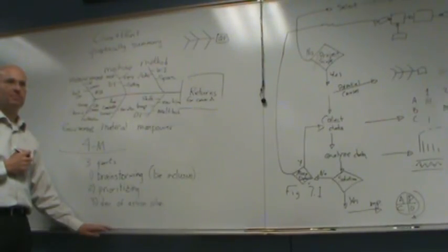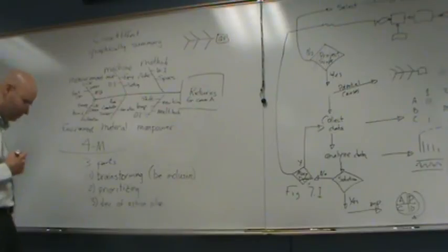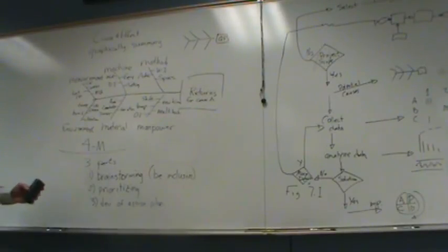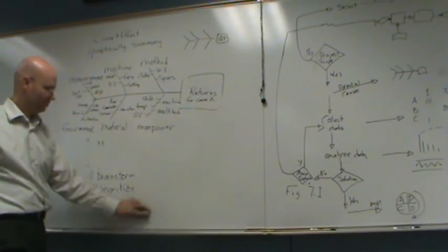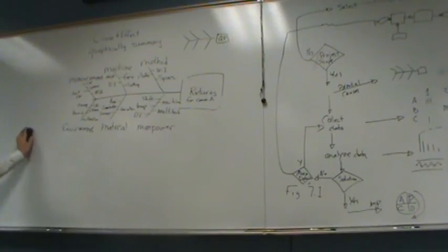And in a lot of cases, you change the ones that were wrong, you do work instructions. We got returns because we got a whole bunch of parts back. The work instructions didn't say to install RTV on a part going to the vibration environment. Therefore, they didn't have RTV installed and they failed because of the combination of the work instructions and the vibration. So now you've had two root causes. One of them is vibration. One of them is that your work instructions didn't tell you to install RTV. And you can kind of see how all the other ones we listed would start going away. Training wouldn't matter because the work instructions weren't there.